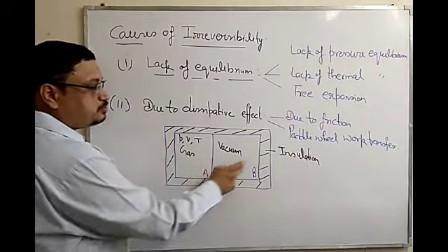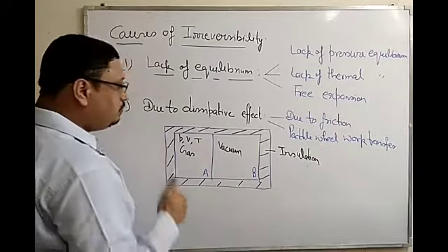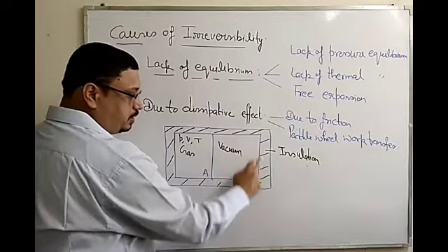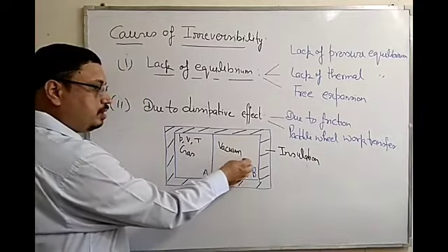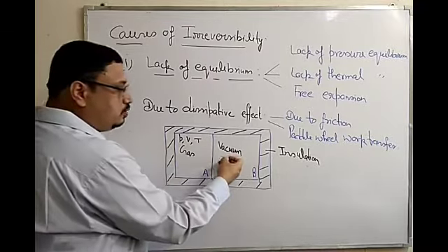And this particular expansion is called free expansion or unrestrained expansion. The reason is that when this gas expands into this particular volume, there is no pressure over here to oppose this expansion, right? So there is no restriction.